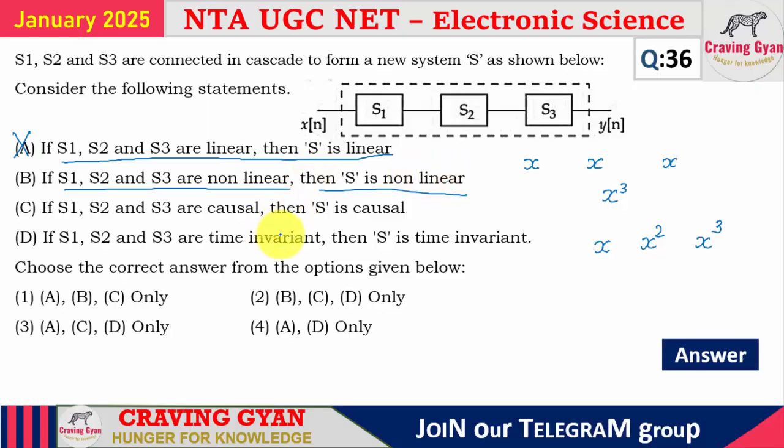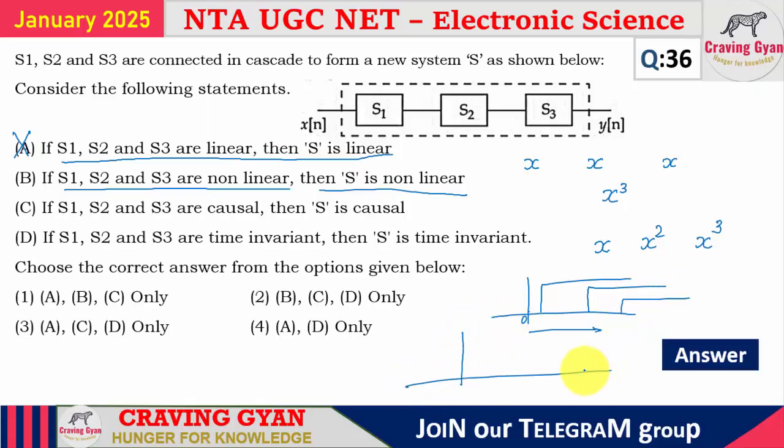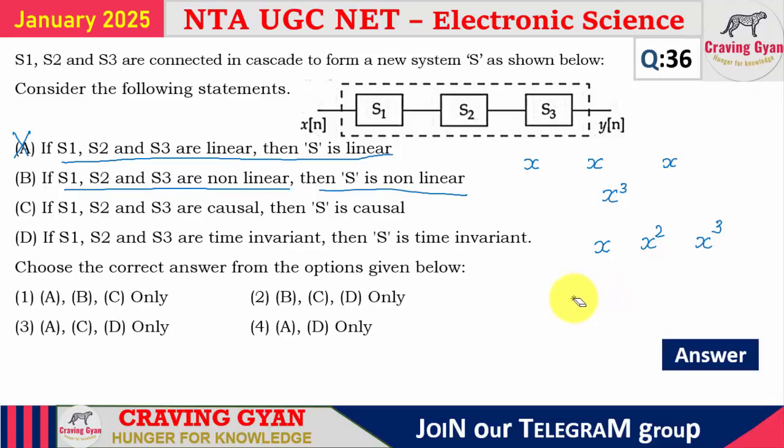See, what do you mean by causal and right-sided signal? Important. In the case of causal, it should be from 0 onwards, and it is right-sided. But if I am telling only a right-sided signal, this is also a right-sided signal, this is also right-sided. So all causal signals are right-sided signals, but all right-sided signals are not causal. Very, very important, right?